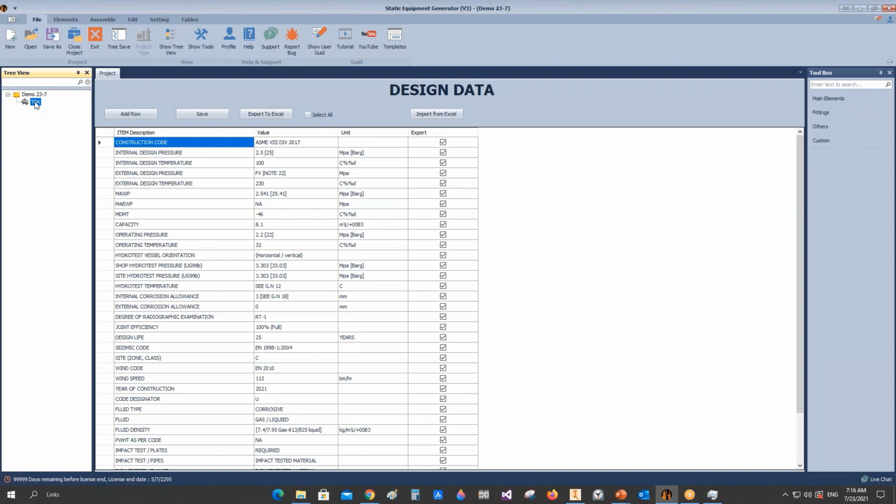Now we will rename this vessel, give it a name, and we will define the design data for this equipment. Now we will rename this vessel as EA 100, for example. Now you need to make a refresh by selecting the node again to refresh this form. Now we will define the design. We will try some different options to know how we can deal with the design.